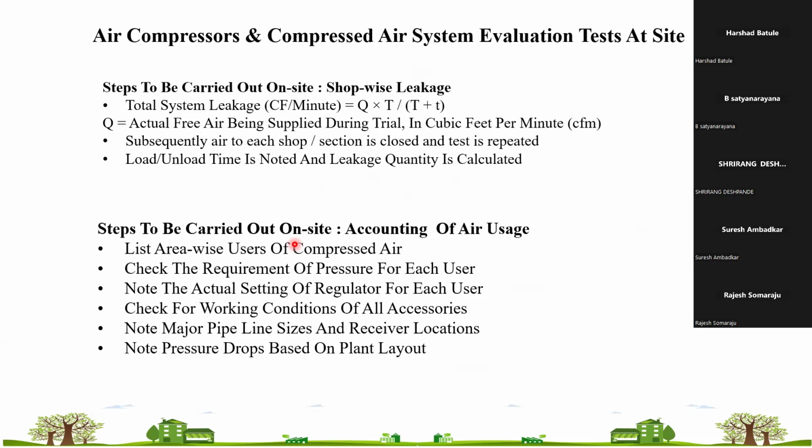So 0.15 is your 15 kilowatt motor and 100 CFM compressor. So 0.15 kilowatt per CFM is your specific energy consumption.